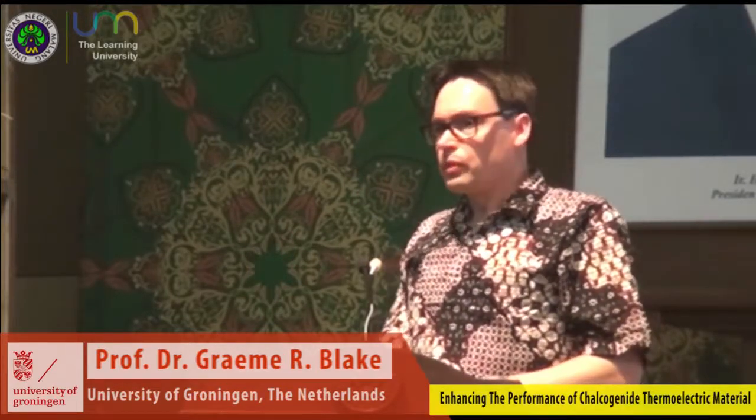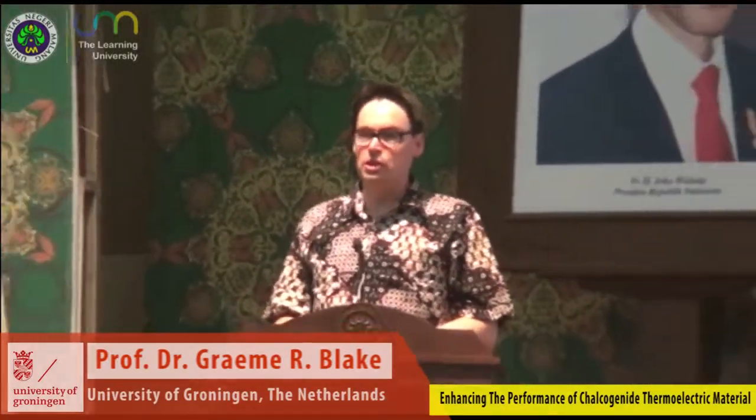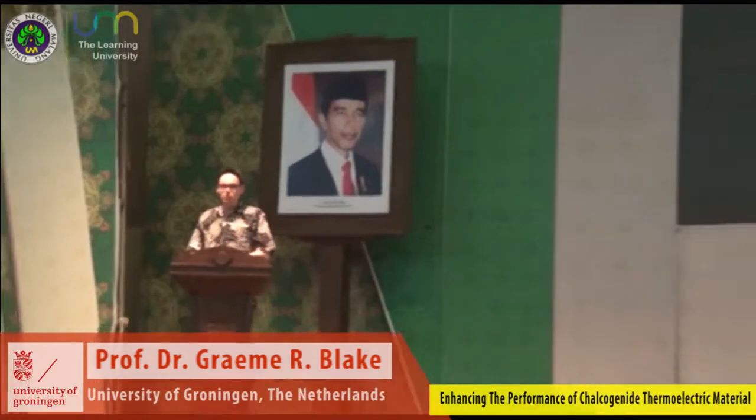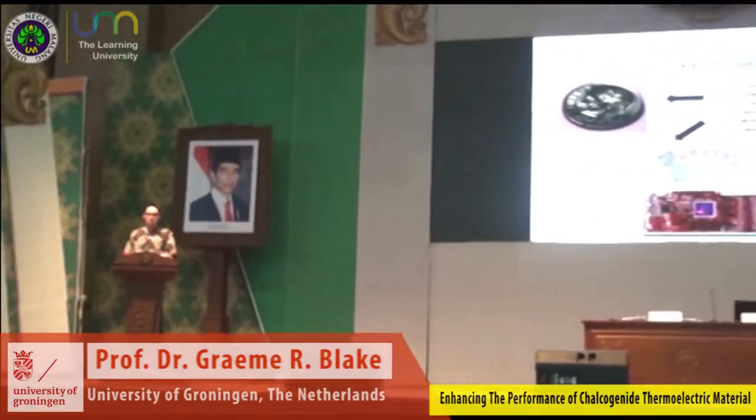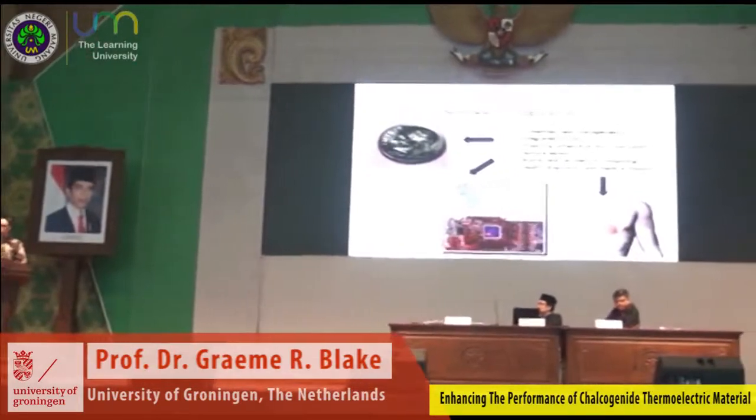So for example, you could use the heat generated in integrated circuit technology to help generate small amounts of power. So maybe that would help in generating power in mobile devices. I should mention there's also a converse thermoelectric effect, which is known as the Peltier Effect. That's when if you apply a voltage to a thermoelectric material, you can generate a heat gradient. So you can put such a Peltier device on a hot spot in an integrated circuit and help to cool it. So in other words, using thermoelectrics as heat management devices in integrated circuits.